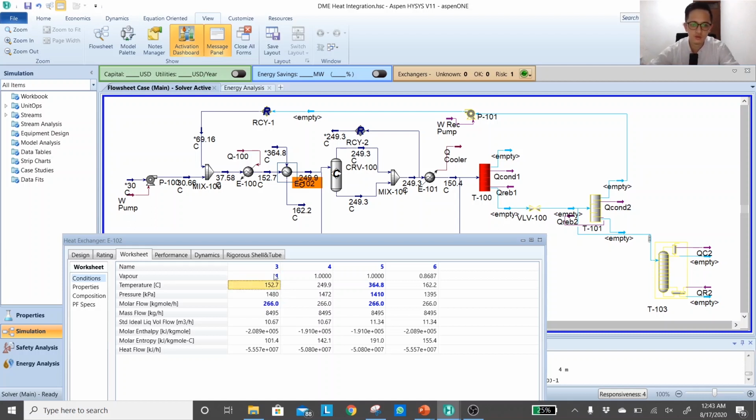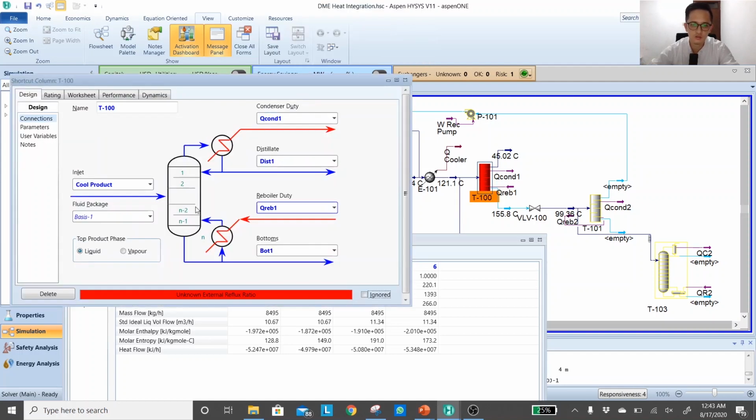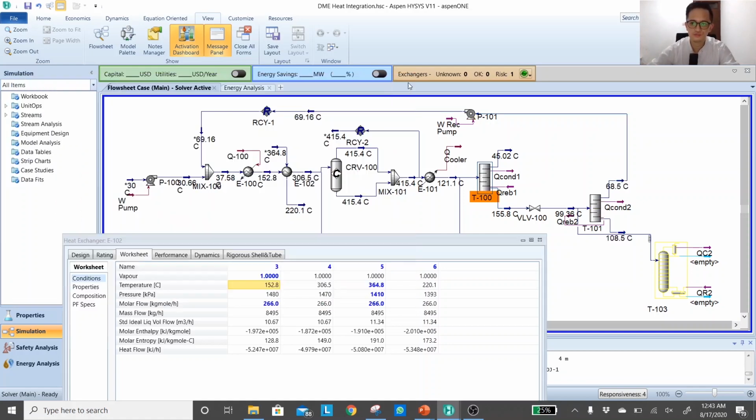I'm going to keep the number, Control C, and just try to trigger the simulation. Maybe I'll help with the complete vaporization first. Okay, that seems to work because now my simulation is already getting a high temperature. That means the reaction is happening. Okay, and then I will connect back my reflux ratio. Okay, it's working.